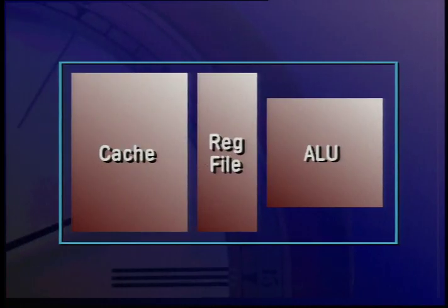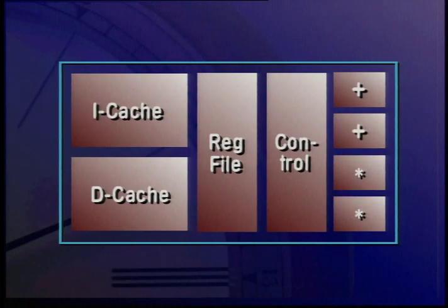Gate counts are constantly going up. What are all those new gates being used for, and how does that affect design? Well, from the design perspective, what they're being used for is making more complex designs. At first, the tendency is to use regular structures: memories, registers, caches, and replicated functional units. Making a memory bigger doesn't really increase the complexity of the design. However, you eventually run out of benefit from regular structures, and when you have exhausted the gain obtained by replicating regular structures, you turn to irregular ones. Those are things like combinational logic, bits of state, pipelines, and control logic.